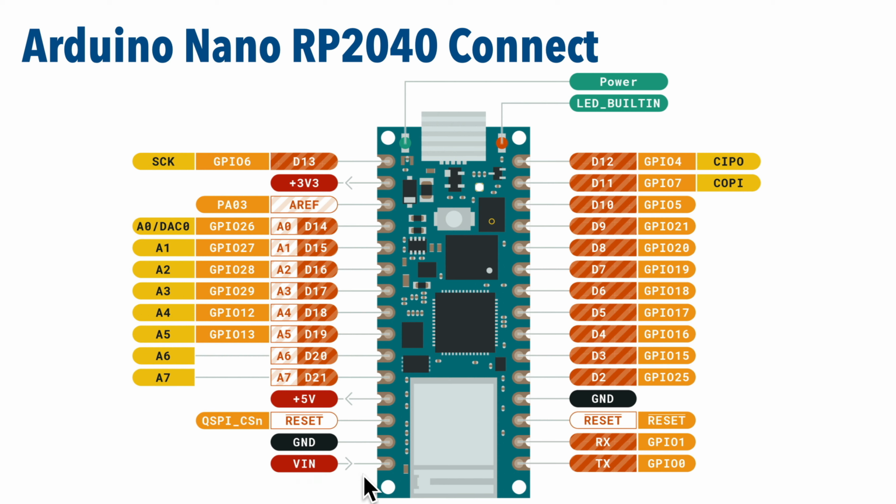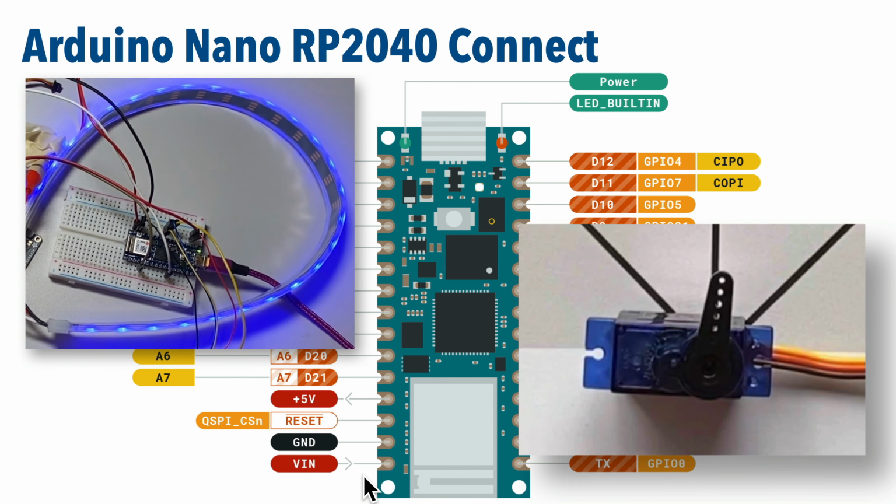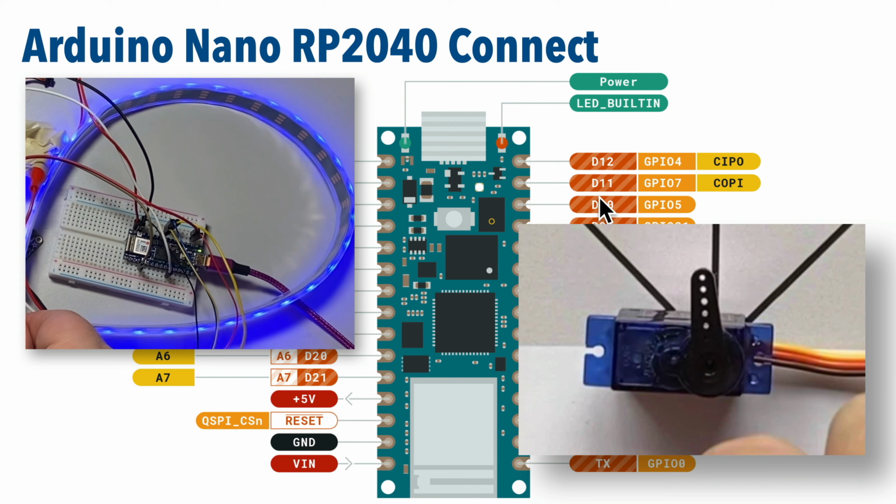Now, as mentioned, you don't want to provide more power than a component can handle. That might even damage some components. But we often do have higher power component needs where VIN makes sense, such as the multi-light NeoPixel strips and strands that we're using, or the servo motors. So when we use those components, we'll plug the power pin into VIN.